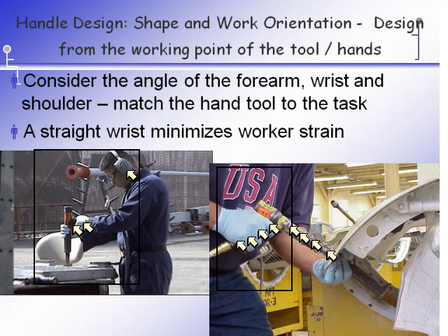One of the things that you may or may not notice about this picture is if you take kind of a close look in this area right here, that's where the pneumatic or the air comes into contact with the tool. And really we have to be careful here with our maintenance and make sure that those connections are tight and well lubricated, because if the air leaks out in this area, the cold air is exhausted right onto the worker's wrist. And as we know, cold temperatures are a contributing factor for the development of work-related musculoskeletal disorders. So that's one of the reasons why wearing gloves is such a good example when working with hand tools.